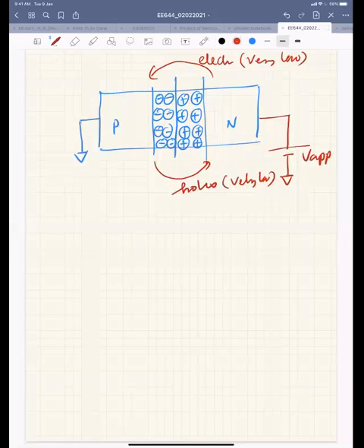your Fermi function is exponential, so a little bit of change in reverse bias will reduce the electron injection exponentially. When you go to negative applied voltage or reverse biasing, it reduces the injection from N to P, or hole injection from P to N, exponentially. So this diffusion current is non-existent. In forward bias you are mostly dealing with the diffusion current, because electrons are injected and then they diffuse. So diffusion current is not there,